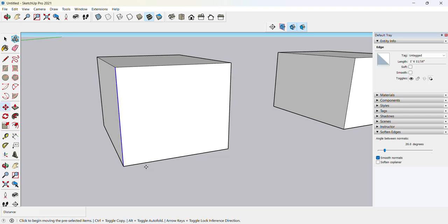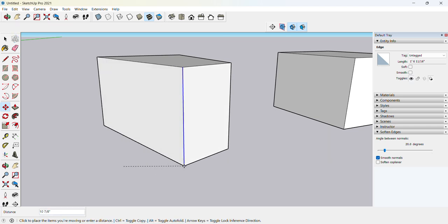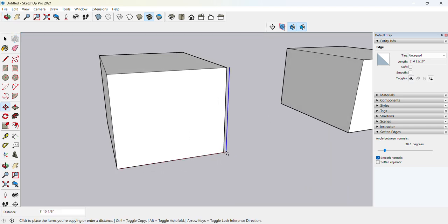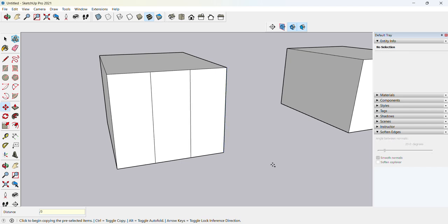Okay. So here I am selecting this segment. I am giving M. This is my base point. And give control. And placing at the edge of the surface. Here we want to divide this surface into 3 or 4 divisions. Okay, for that here I am using the division symbol. Divide of 3. Enter. See? So like this we can divide a surface simply.